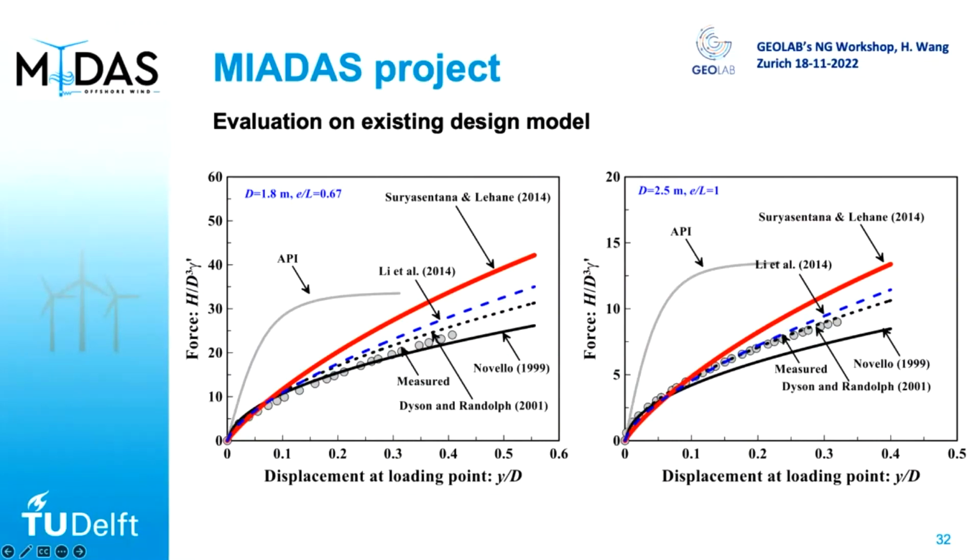So the pile configuration completely changed, the mechanism changed. So even if you don't consider the rotation spring or all the other components, the PY model itself doesn't work. So people should improve the PY model first. But as a follow-up of your question, yes, when we get the PY right, when the pile becomes much shorter,